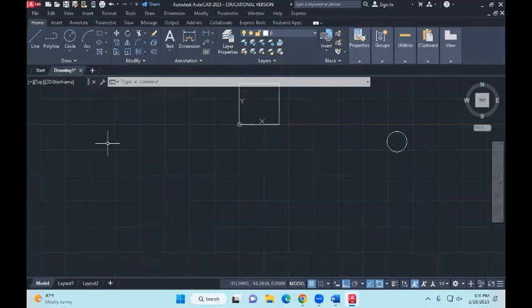So let's start again. Let's try to draw a square with a side of 50. Okay, so line. I would like you to pay attention, so you'll have fewer questions to ask and there is less confusion. Maybe as I'm going along, you can do the same thing in front of you. So I have executed the command, and it says specify the first point. I'm not going to use coordinates anymore, so I'm just going to specify it anywhere on the blank page. So let's start from there.